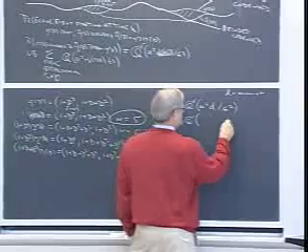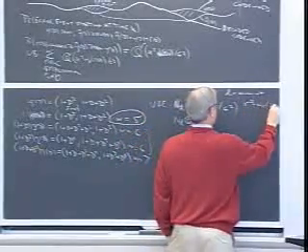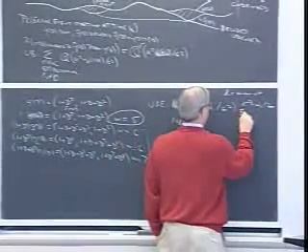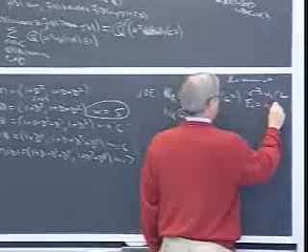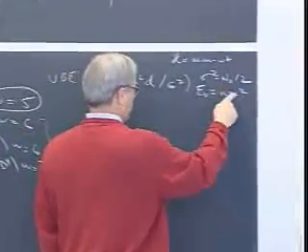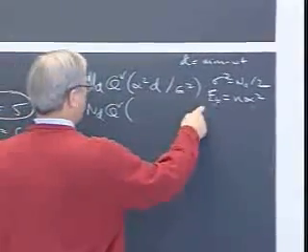what is sigma squared equals N naught over 2, and Eb equals n times alpha squared. The energy per transmitted bit is alpha squared. We're going to transmit n bits for every information bit.